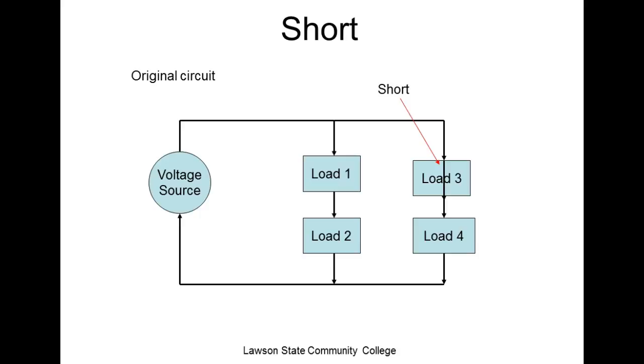Because the breaker is not looking for a short, it's looking for a short circuit. Right? You understand that? So yeah, you get that short out there on that long extension cord, you can catch your house on fire real easy, and your circuit breakers won't ever even trip. So this guy right here is going to have big problems, because if these two had the same opposition, it's going to be trying to produce 4 times its work.